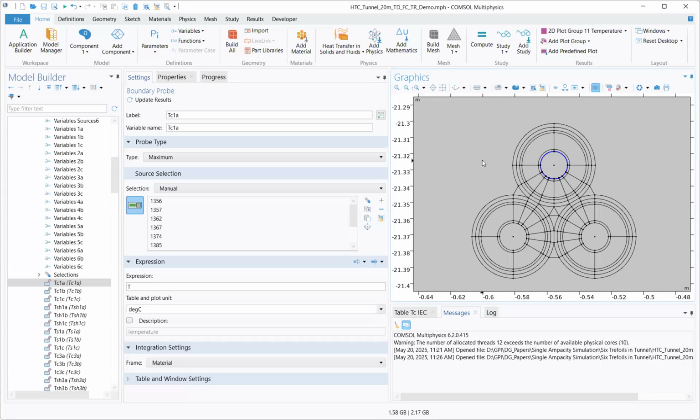The way to do it is you pre-compute the loss with the magnet, or whatever the version of ANSYS is, and then you import it here. But of course, the bottom line is not the same. There's another workflow, and it's more work. You have to pre-compute it, or you have to set up two models. You have the electromagnetics model, then the ANSYS fluid flow and heat transfer model, and then you need another model to integrate both of them. It's called Workbench. So anyway, it's very complicated.